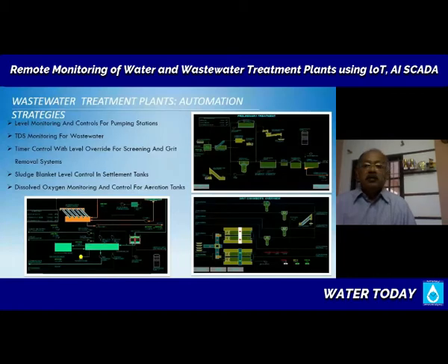If I've seen the TDS going above 10,000 ppm, then it is a concern that there is external ingress into your wastewater, considerable amount of external ingress. TDS can be conductivity or salinity, as we call it, can be a good indication of what is coming in from outside.